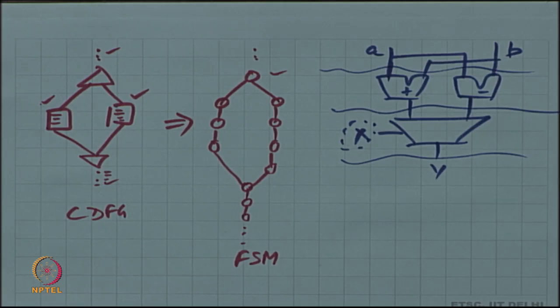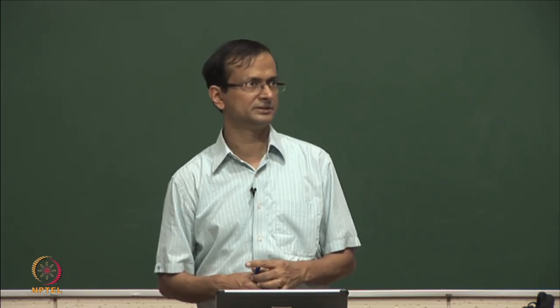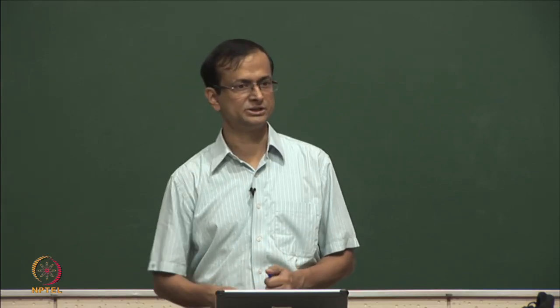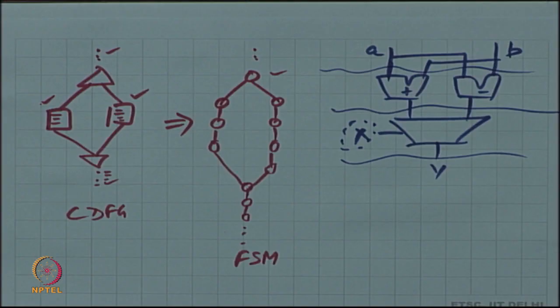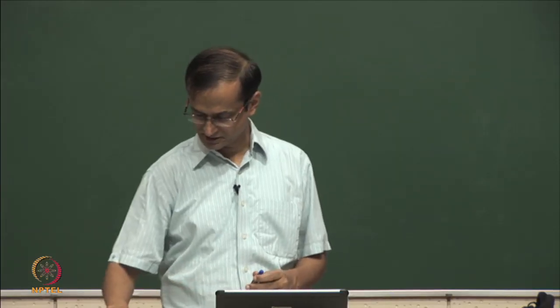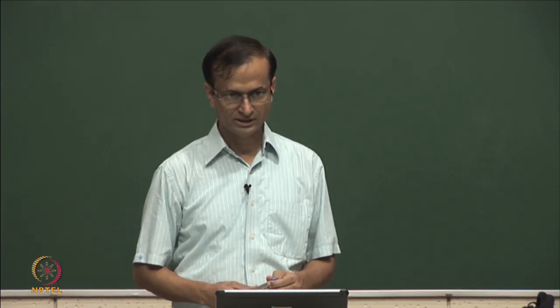But this does avoid the need for splitting the FSM into multiple parts and joining, particularly when the statements are so simple. If they are complex, then it is usually worth it, but if it is something like just one state each, then it may be worth considering transformations like that. This should also illustrate the general mechanism for how to handle if statements in synthesis.